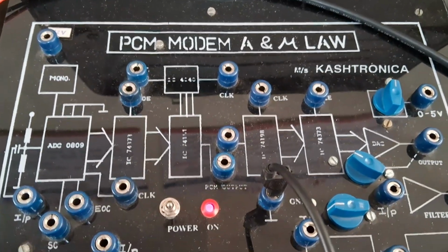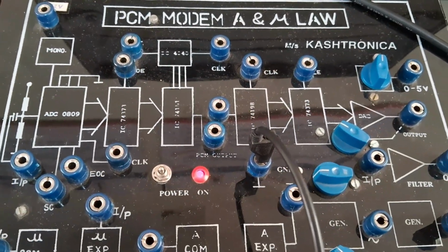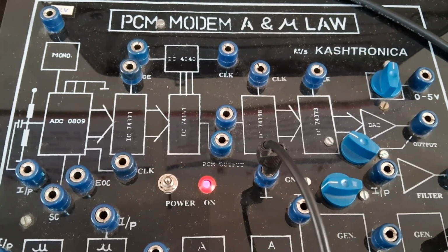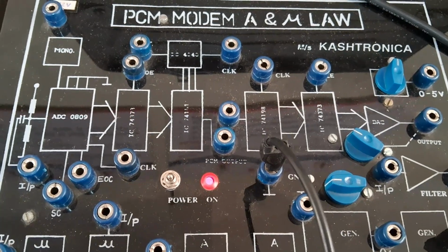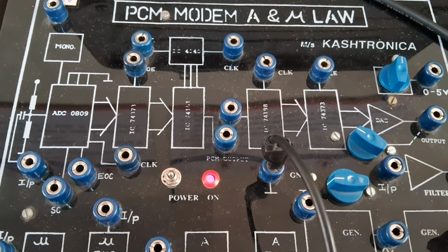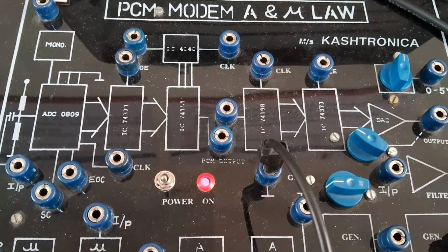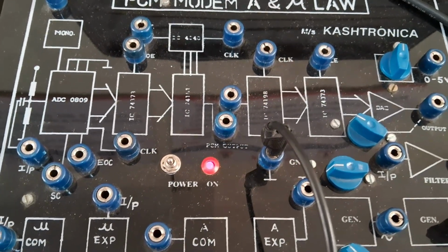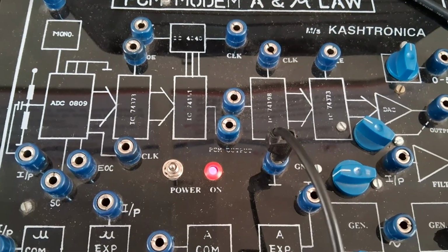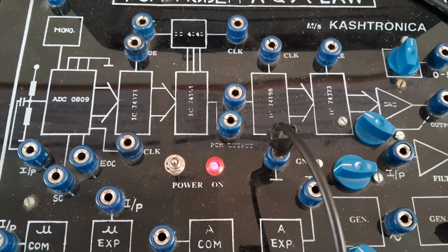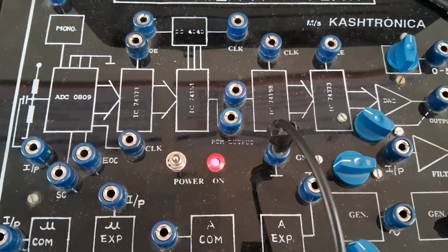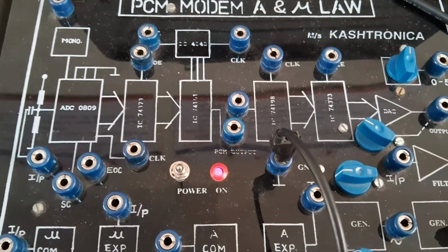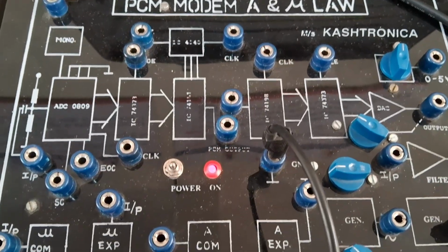So what are the basic blocks of pulse code modulation? The first block is a sampler, the second is a quantizer, the third block is the encoder, and then a parallel to serial converter. The sampler is simply a multiplying of the pulse sampling wave and the analog signal. Quantization is approximation of the signal, and then encoding, that is converting the analog value into digital data, and then the parallel to serial converter.